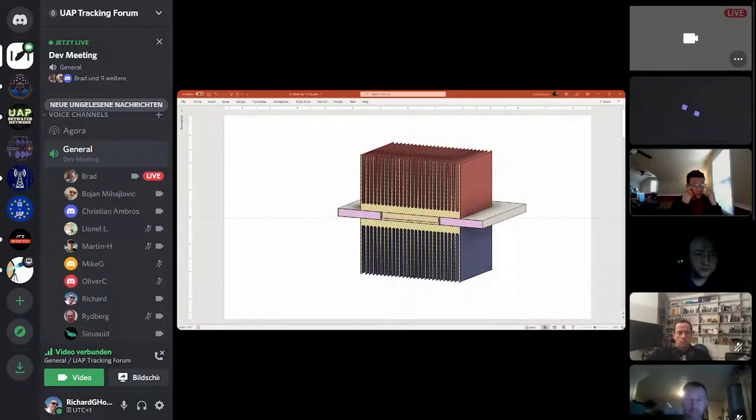All right, so for the duct, the main body of the climate control unit, we're looking at 5mm ABS, so it's pretty thick. The nominal thickness of a peltier module is about 3.75 millimeters, so there's a gap there that we have to close. Also, we're setting this up as a forced convection heat exchanger. Pretty simple. You've seen these in commercial buildings. The heat exchanger in a duct basically fills the whole duct, so you have the maximum amount of surface area to do heat exchange across. That becomes problematic with peltiers.